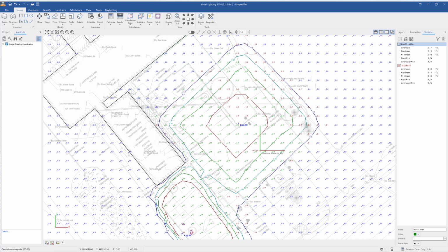Okay. So back in here, this is really tight to the property line, but it's a really wide area. This is where your selection is important. This time I'm going to use a type 2 fixture at 20 foot. And we're going to just place it somewhere here in the middle, right off the edge of the pavement. And recalculate. You can see that one throws left and right really far. It does not have a lot of light coming off the back, so it looks like we're good with trespass. We're not going over the property line with more than 0.2, and it's lighting up that entire area.